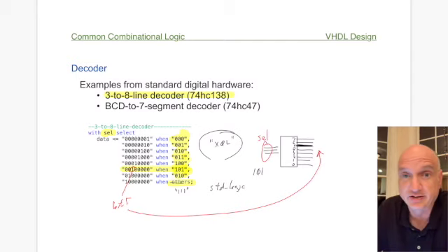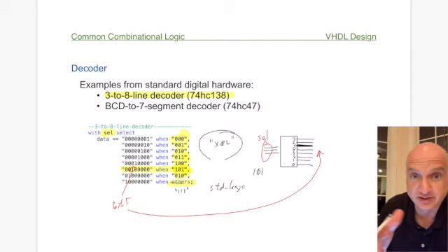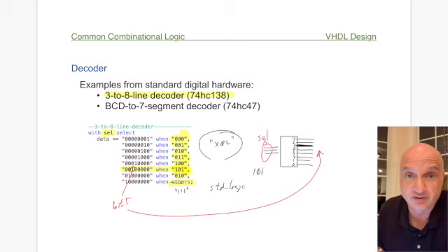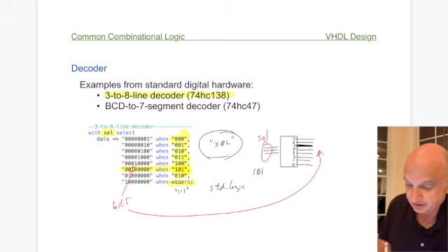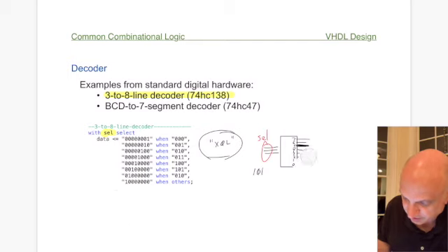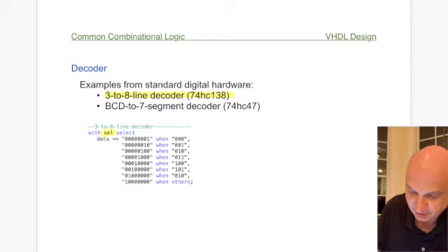In fact, it would likely create what's called an unwanted latch, and that's something that's going to be the bane of our design. We're going to be watching that throughout the whole term to make sure we don't accidentally generate these latches. Basically, the others clause is required in order to make sure we don't have that kind of a situation. So we're going to stick with the others clause on anything that we use for combinational logic.